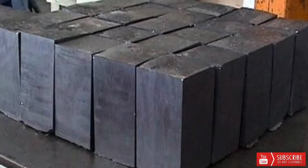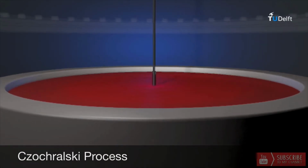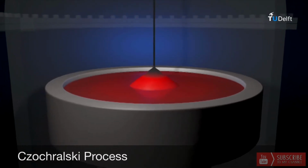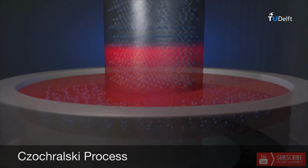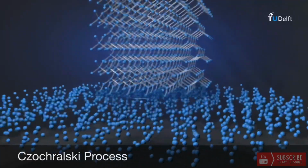We can either proceed with this pure polysilicon to make polycrystalline ingots, or we follow Czochralski process or float zone process to make monocrystalline silicon ingots. In the process of ingot making, attention is given so that all atoms are perfectly aligned in a desired structure and orientation by controlling temperature and other atmospheric conditions. This process is very expensive, and that's why monocrystalline solar panels are also expensive, whereas polycrystalline ingots are manufactured by directly casting melted polysilicon crystals in a dedicated crucible.